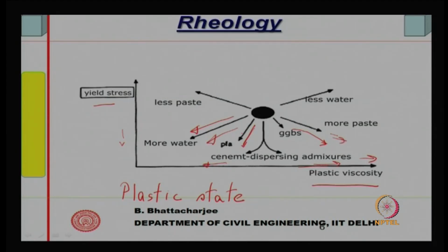So, this gives us some idea how rheological properties are changed, and this would be more clear when you look at the rheology of concrete, fresh concrete, workability, etcetera. So, one side is fly ash, the other extreme is of course rice husk ash, which increases the superplasticizer demand. As far as rheology is concerned, fly ash gives you a plasticizing effect like adding more water, but GGBFS, which is angular in nature, does reduce the yield shear stress, but of course increases the plastic viscosity.